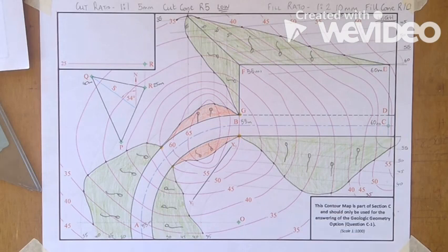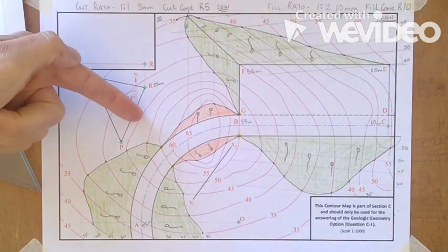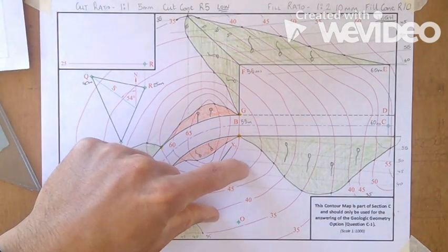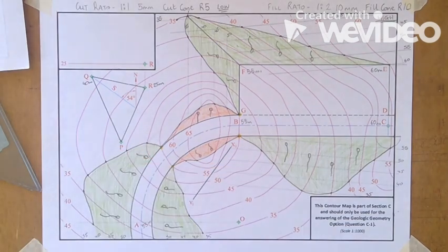So we already know that if you look along the strike line, you will get the dip or the angle of the stratum of ore underneath the ground. So what we're going to do is we're going to project out a view this way, set it up here in our X1, Y1 line, and that'll give us the angle to the horizontal plane.